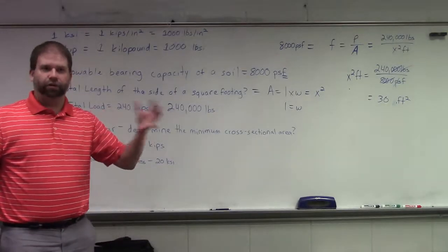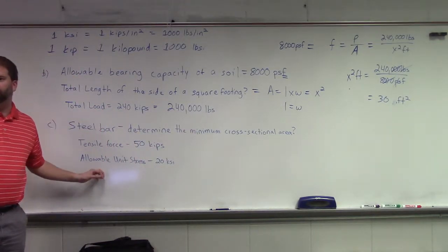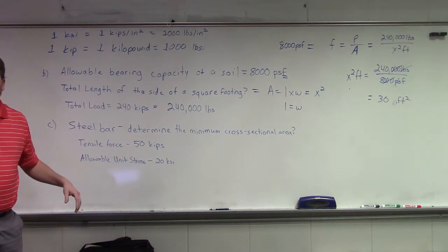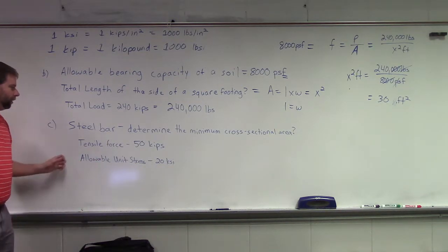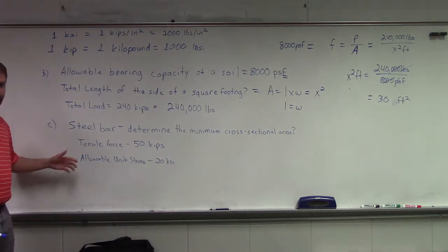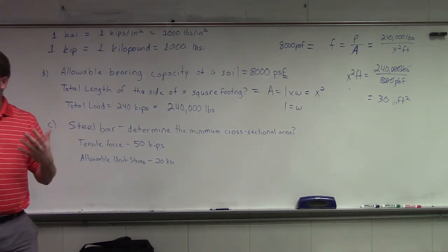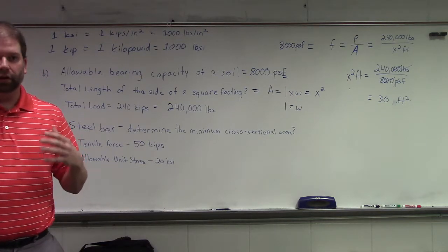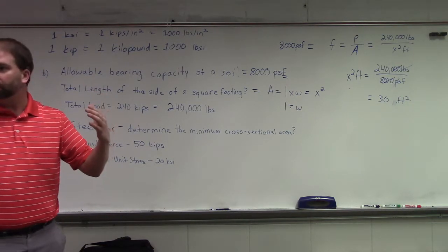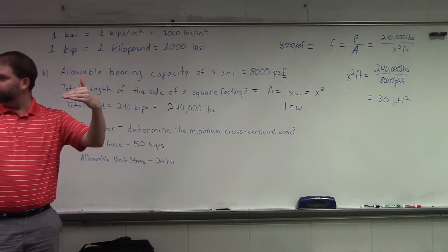So we're dealing with different types and different grades of steel. Most frequently, you're probably going to be working with grade 60 steel. Okay, so we're answering part A again. We're looking for the cross-sectional area, right? Because here you have a stress, and here's where we're allowable. So here we're trying to figure out how to size the member for the situation we have. We know the loading, and we know our maximum capacity.